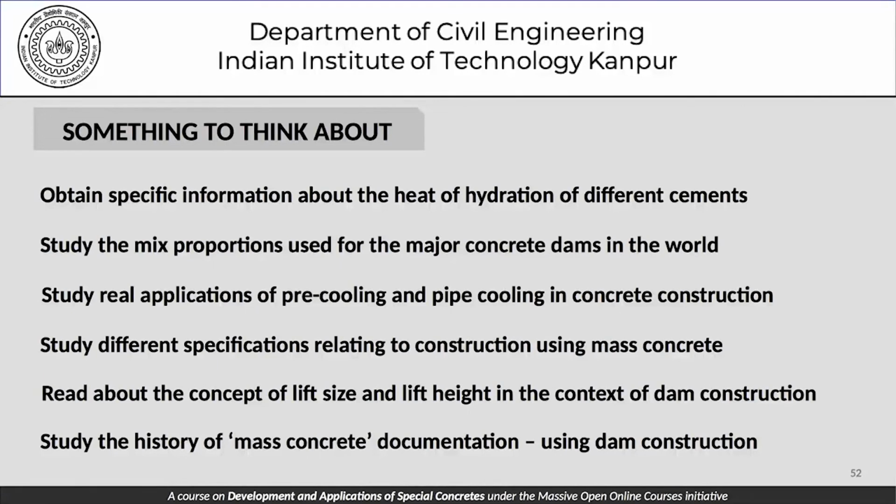Read about the concept of lift size and lift height in the context of dam construction, and planning for dam construction. What should be the sequence of operations? At what stage should we cast the next lift? Because that really determines the temperature of the concrete against which we are casting the next lift. Study the history of mass concrete documentation using dam construction. These are some of the things that could be very interesting for you to do as an outcome of our discussion, which has been largely qualitative, but can be interestingly quantitative as far as heat of hydrations are concerned.